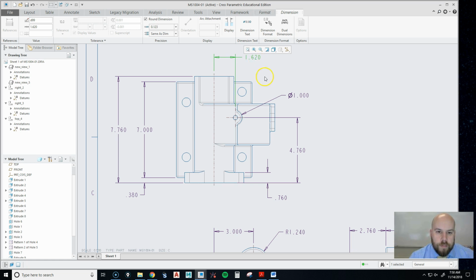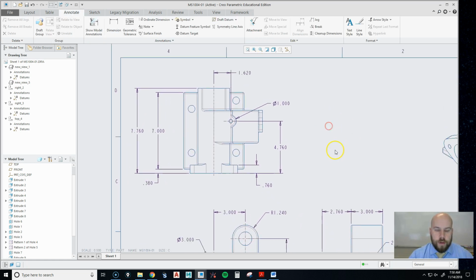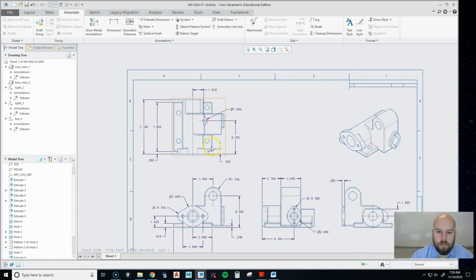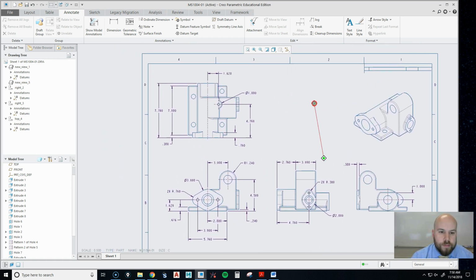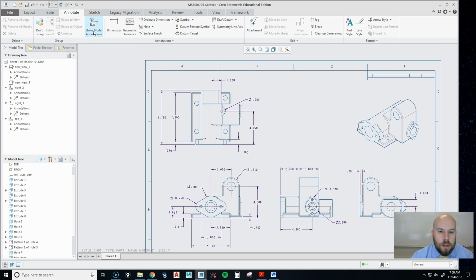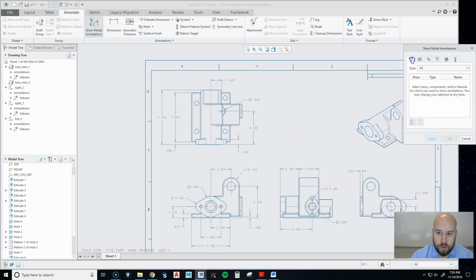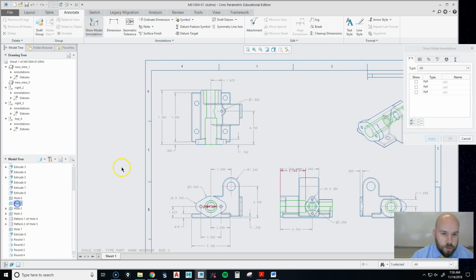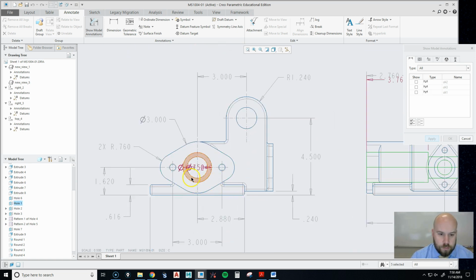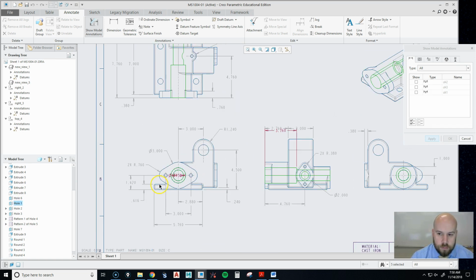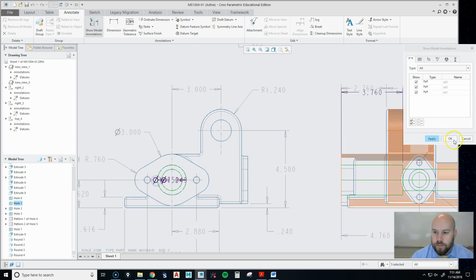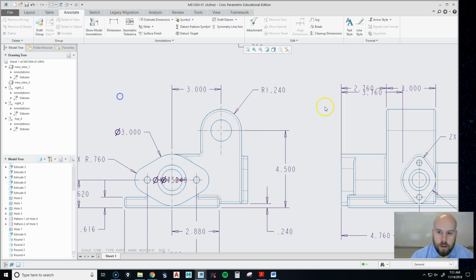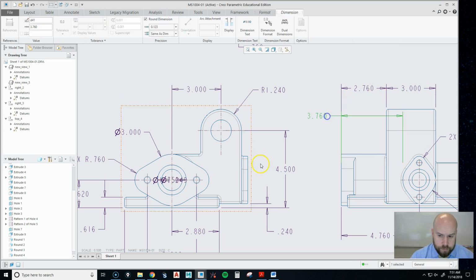Alright, this view is probably going to get a little messy. If I need to, I'll project another top view. No problem. So, next one, dimension, hole number 1. So, let's see, I have a depth, and I have 2 diameters. Okay, I'll move my depth over here so I can see it pretty well. Pull my diameters out.